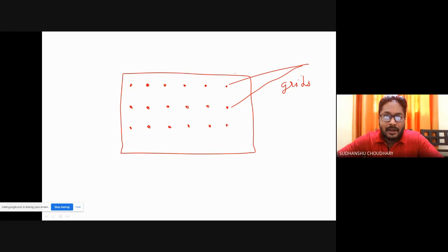Now, the spacing between these two grids, or maybe these three grids. What is that spacing? Let's say we start from here and we end here. This spacing is 2 lambda, and 2 lambda is equal to the minimum feature size, that is channel length, as we already commented.